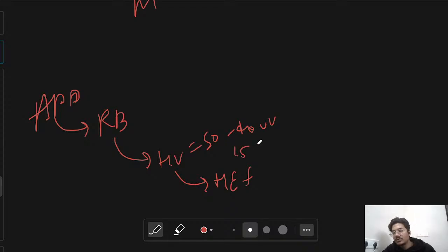The operating voltage is too close to the breakdown, causing excessive noise, so the bias must be controlled precisely. The problem that limits gain: even though theoretically a very high gain, approximately M equal to 10 to the power 4, is possible, in practice microplasma, like a small defective region with a lower breakdown voltage, causes uncontrolled local breakdown.